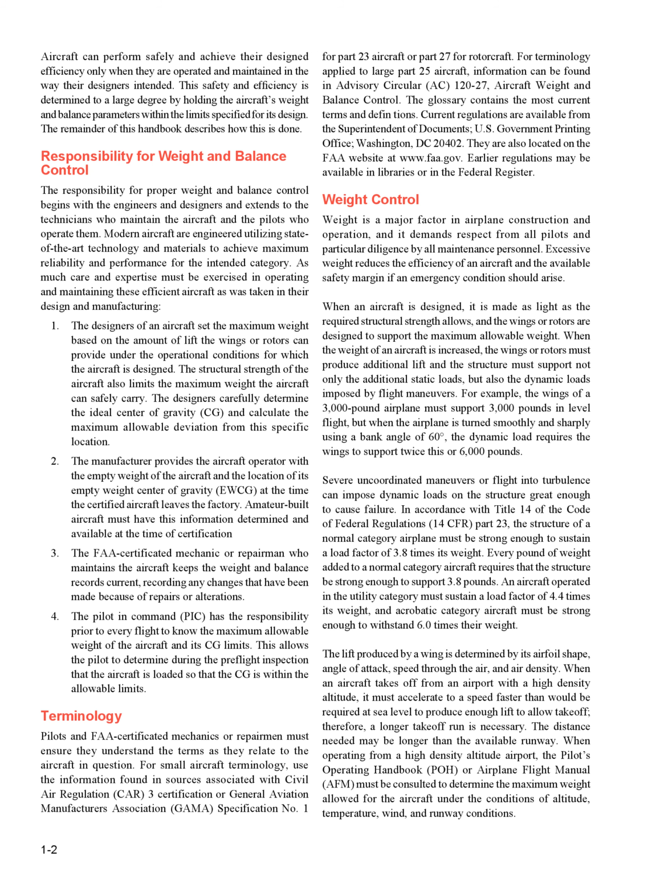4. The pilot in command (PIC) has the responsibility prior to every flight to know the maximum allowable weight of the aircraft and its CG limits. This allows the pilot to determine during the pre-flight inspection that the aircraft is loaded so that the CG is within the allowable limits. Terminology.